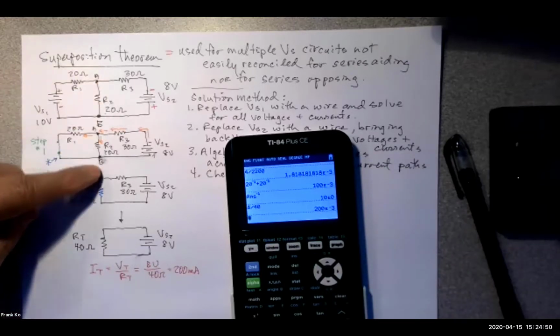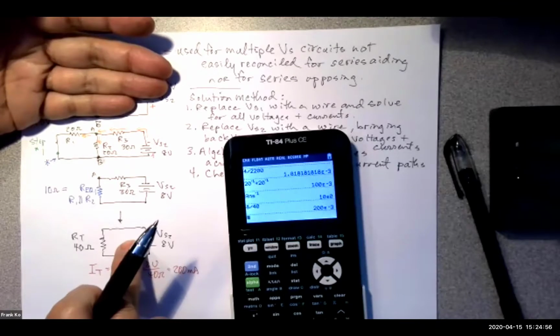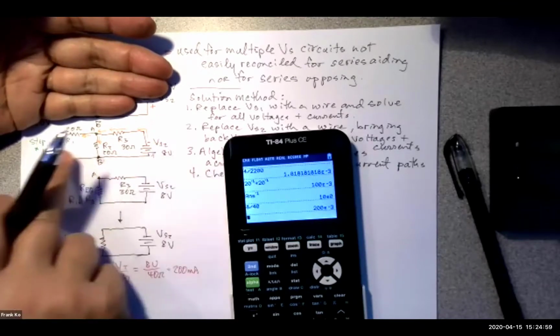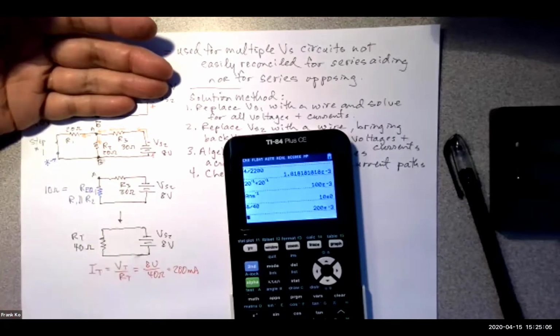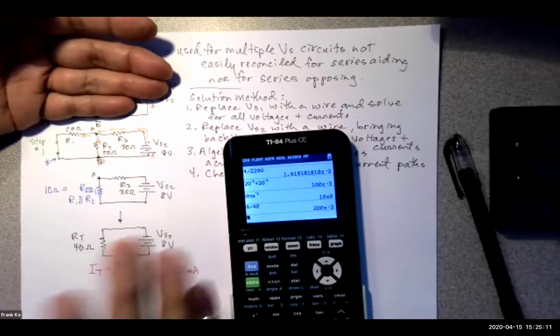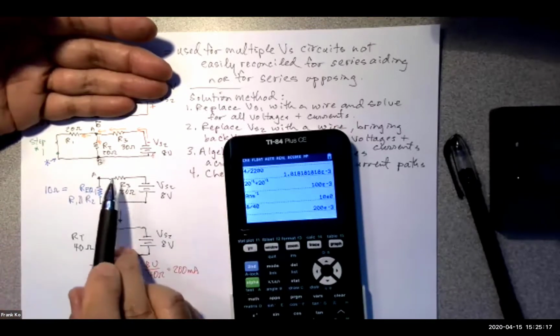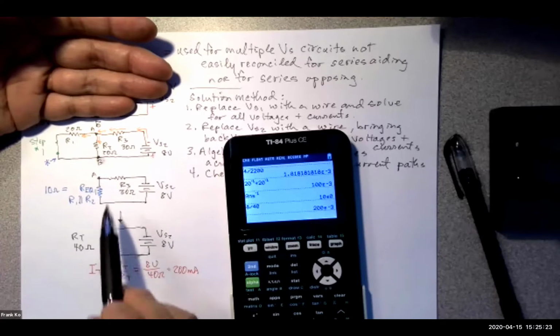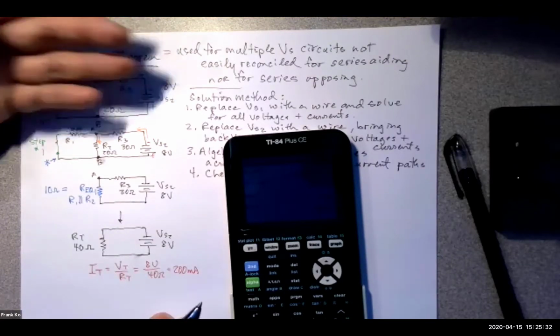Is this the same method as we employed previously for analyzing our circuits? Here's the voltage source. You put your eyeball farthest away from it. You look at the relationship between the resistors. You discover R1 and R2 are in parallel. You calculate those, reciprocal, shortcut, product over sum, whatever, doesn't matter. You're going to end up with 10 ohms. The 10 ohm REQ1 has a very unique relationship with the original R3. They're in the same current path. They're in series. You combine these two to a single total, 40 ohms. And then 8 volts into 40 ohms gives us 200 milliamps.